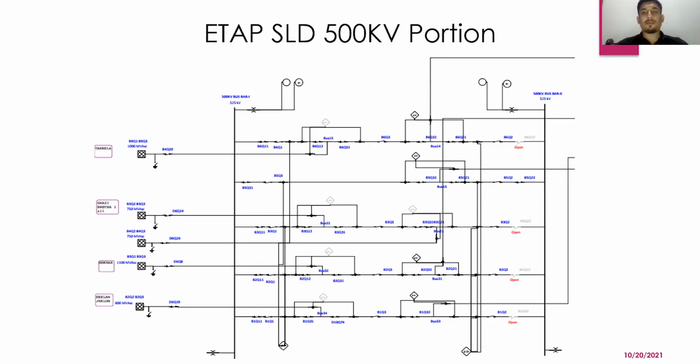Here, a 1.5 breaker protection scheme is implemented, and the bus bars are protected by using current balance scheme or differential protection scheme, and the nodal bus connections have been protected by differential protection scheme. Also, we have here implemented voltage and frequency protection.